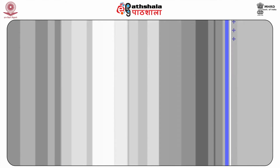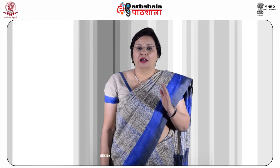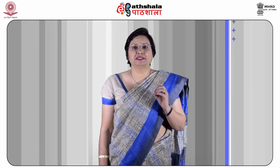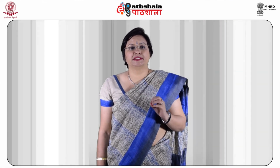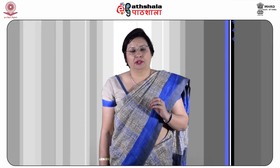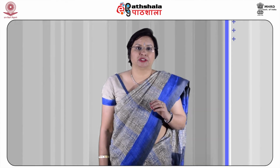So, now we move to alkalinity. Hardness is commonly confused with the term alkalinity. Alkalinity expresses the amount of acid, that is hydrogen ion, which water can absorb as buffer before achieving a designated pH.